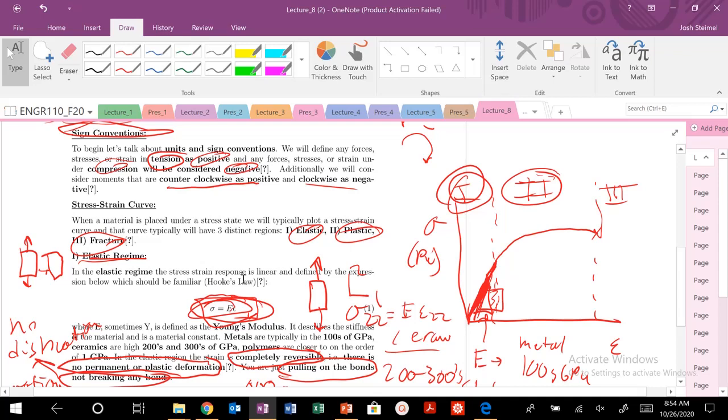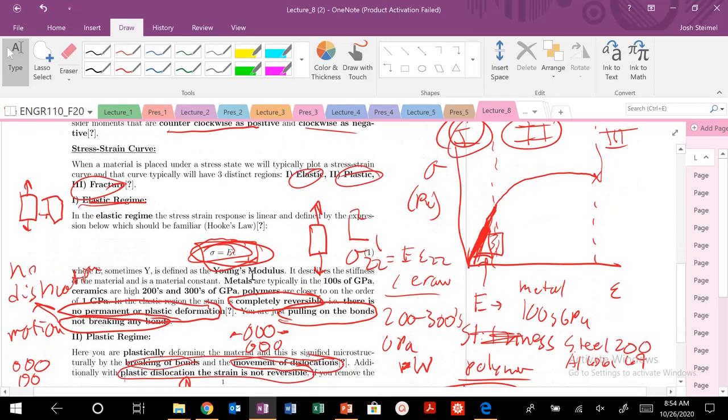In the second regime, these are all empirical theories. We do not have a framework or first-principles equations that can relate stress and strain here. We'll talk about strain hardening in a second, but I forgot to mention the first regime. We can identify the stiffness here. Young's modulus, we'll talk about language in a bit, is a measure of stiffness. We can also measure the yield strength and the yield strain.